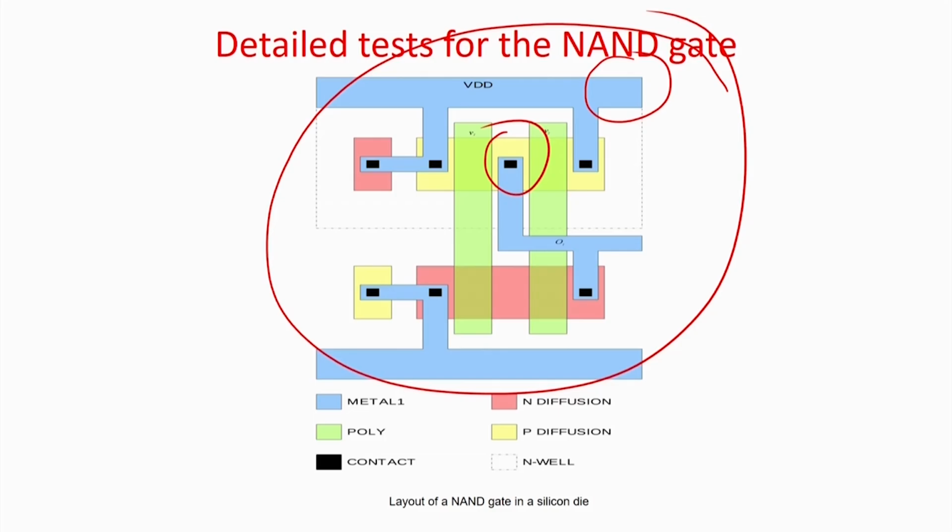So what I mean to say is that testing in the case of VLSI can be as simple as testing the functionality of a gate to as extreme as looking at the lines of the fabricated IC. So now you can understand, for a simple NAND gate it can become so complex. Now we are living in a world of system on chips and network on chips. So what optimization is required, what do you have to abstract, and what level do you have to go to? This module will try to tell you what is a practical level possible to do a test within a particular amount of time, so that it becomes profitable.